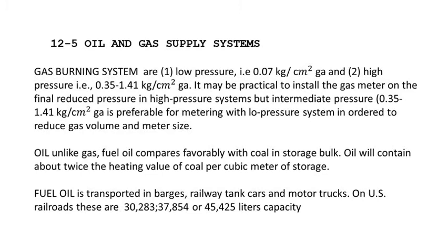It may be practical to install the gas meter in the final reduced pressure in a high pressure system, but in an intermediate pressure of 0.35 to 1.41 kg per centimeter squared is preferable for metering with a low pressure system in order to reduce gas volume and meter size. Unlike gas, fuel oil always compares favorably with coal in storage bulk.